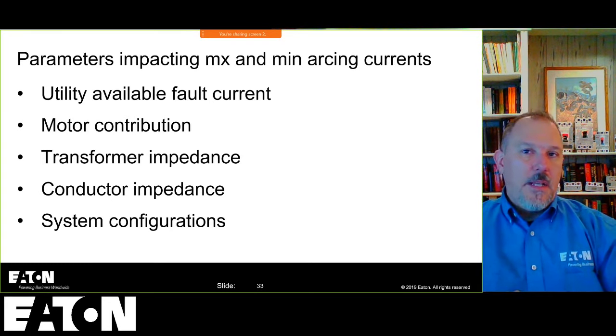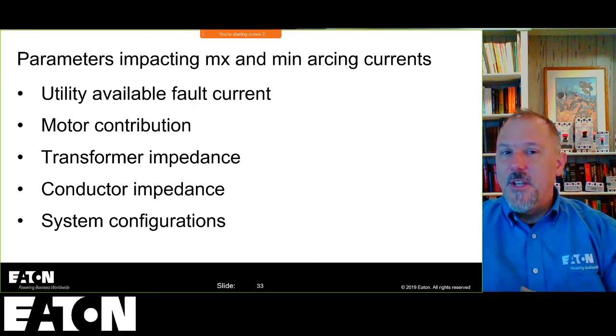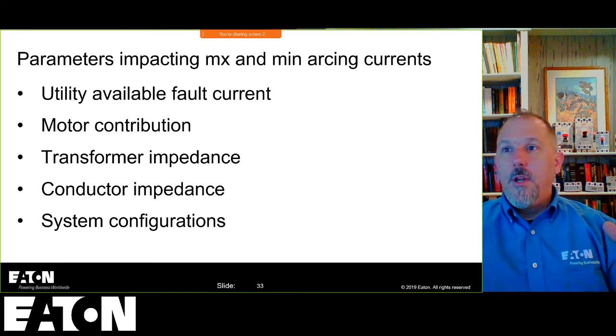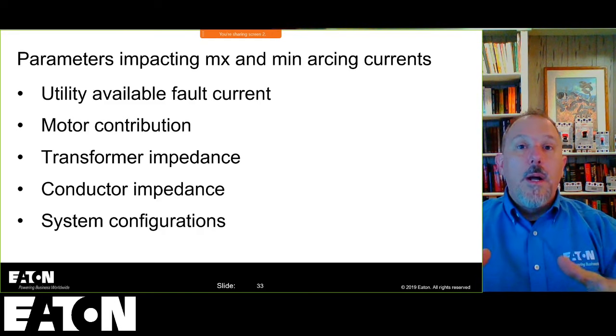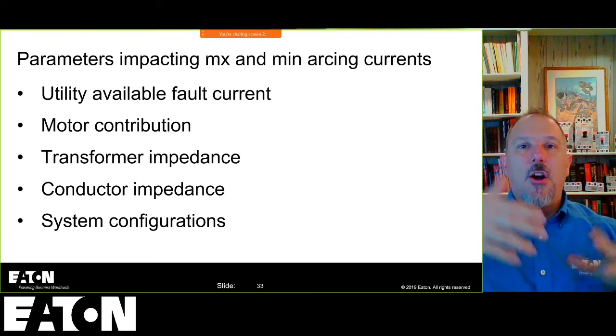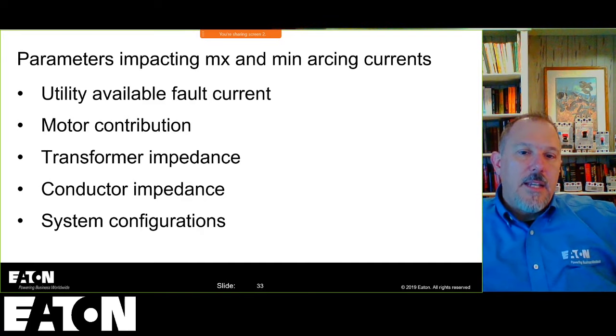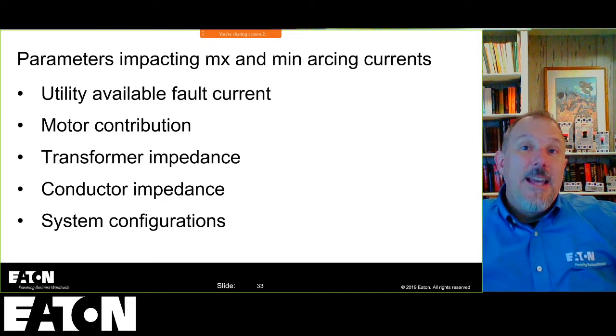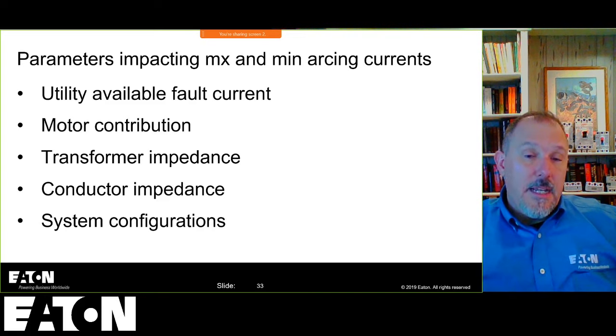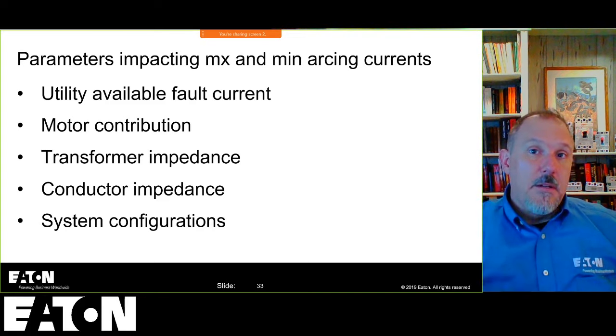Your conductor impedances. And the reason I put the conductor in there is because a lot of times we'll do our analysis in the beginning based upon we're not really sure of what the system's going to be. So we create and estimate our conductor lengths. So it's important for us to do our analysis after the as-built drawings are published and update all of our studies once we have the as-built done.